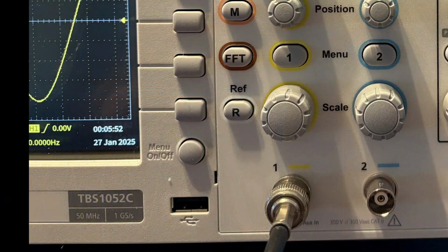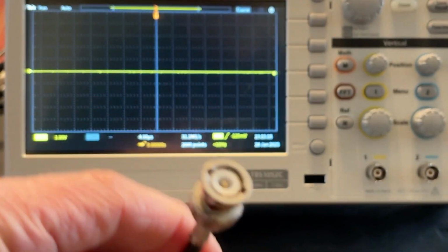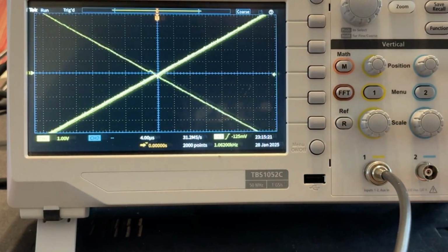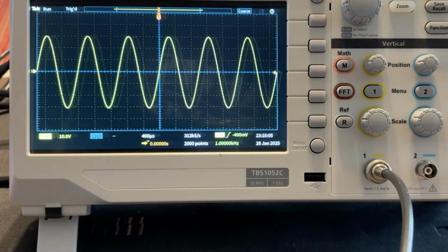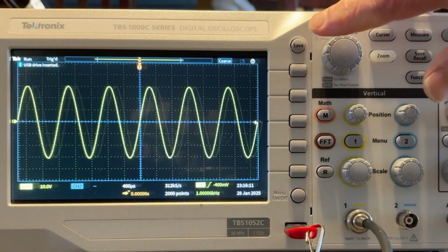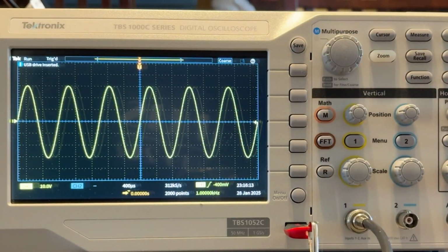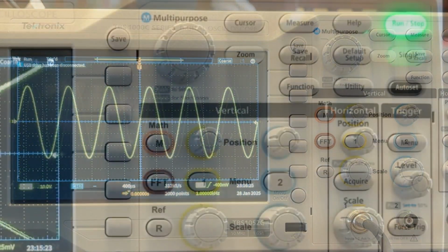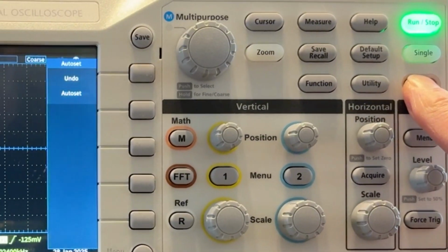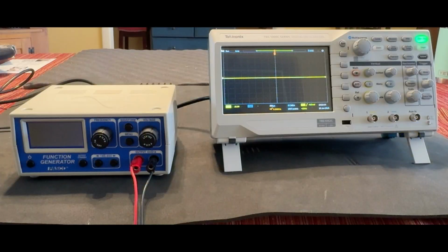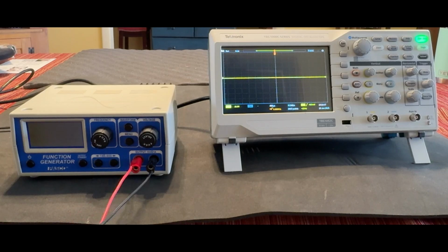You will use the Channel 1 input to connect different devices to the oscilloscope. It uses a BNC type connector for the input signals. To make screenshots, you'll use a flash drive. Plug it into the USB port on the bottom right of the display and press the Save button. Finally, pressing the Auto Set button will often set up the screen to give you a good initial view of the waveform.